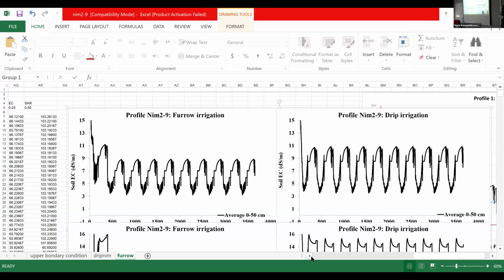Is there any question? I'm ready to answer you. And which crop was planted? Here, as an example, we use wheat. And that can handle that amount of salinity? We don't have any issue. No, the soil EC is less than that during the growing season. The growing season is winter. Yeah, winter, summer. So 5 will be the maximum. Yeah. So if you would like to lower it even more, you will have to add more leaching, basically. Yes. Okay.